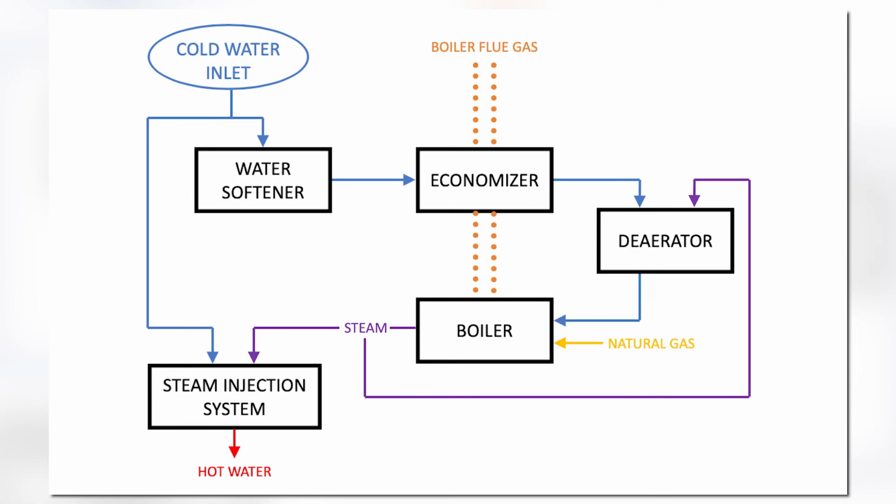The subsequent example will follow a boiler system that contains a heat economizer on the flue of the boiler and a deaerator that pre-treats the boiler feed water. This is a fairly standard setup and moderately complex. When analyzing a boiler system, you should follow the flow of water and analyze each piece of equipment in the order which water reaches it.